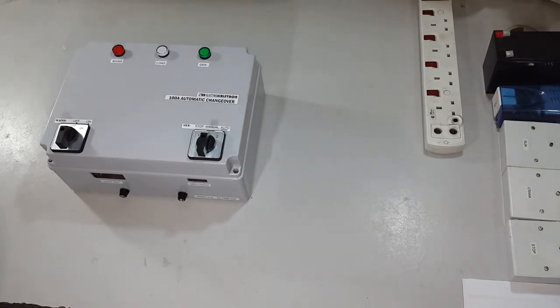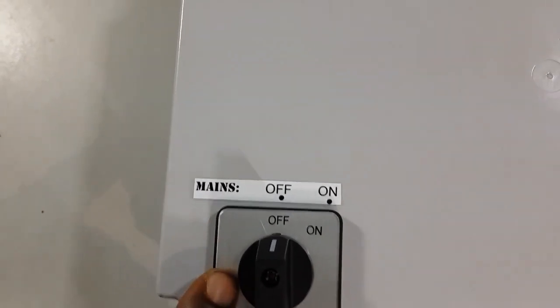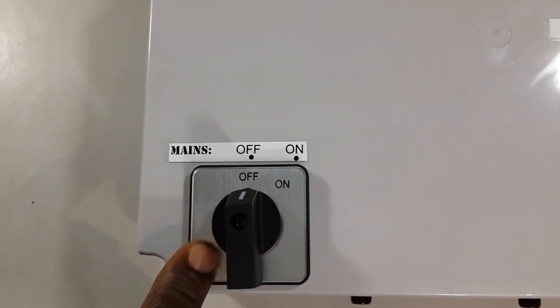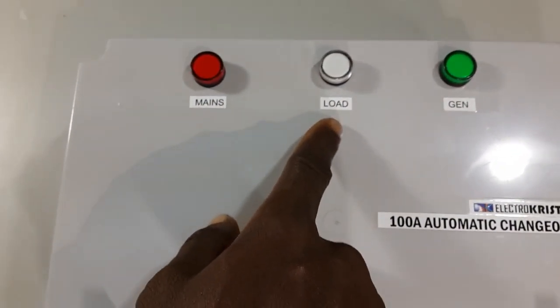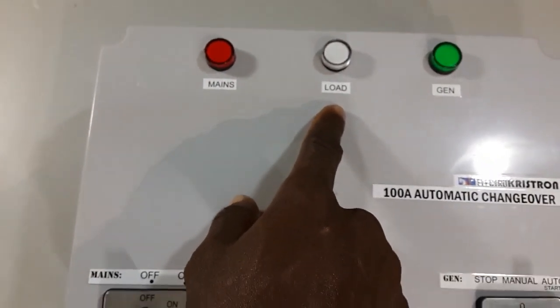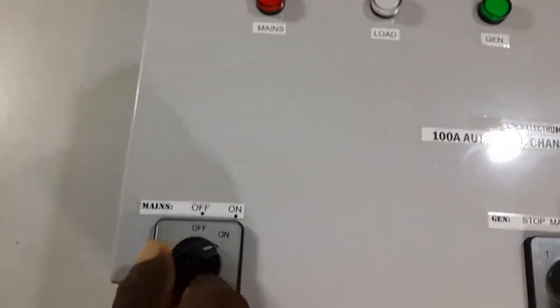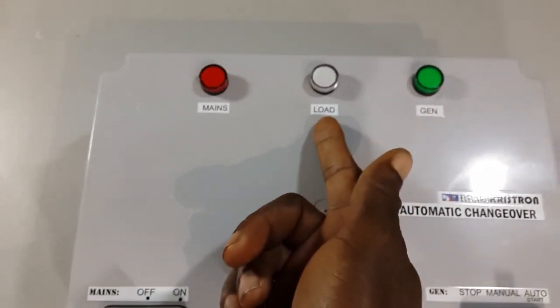There are two switches on the front, as you can see, which allow you to select which of the functions you need. The switch on the left, which is this one, is essentially for engaging or disengaging the public mains if it is available. In the off position, even if the public mains is available, it doesn't allow the public mains to connect to your load, which means that it doesn't engage the public mains to feed your load. But if you leave the switch on, then as soon as public mains is available, it allows the public mains to connect automatically to your load.